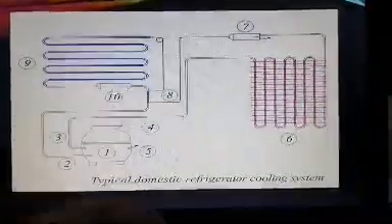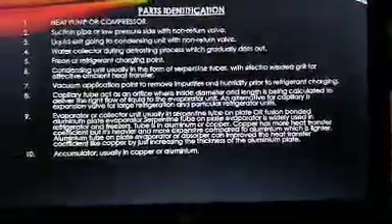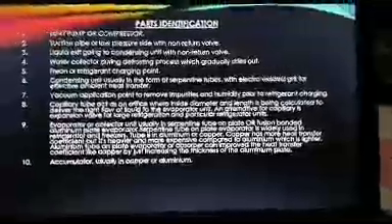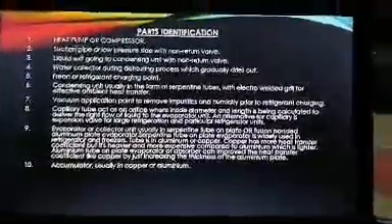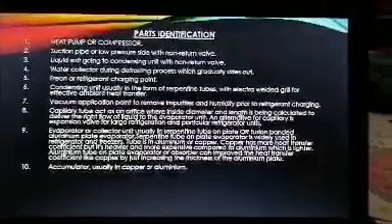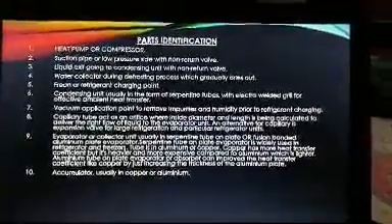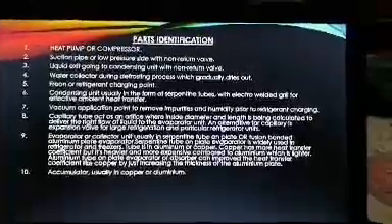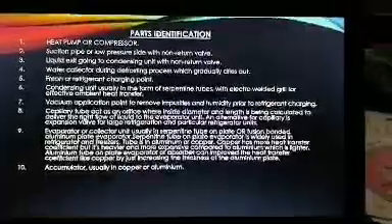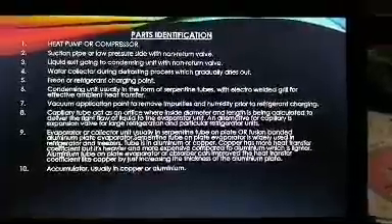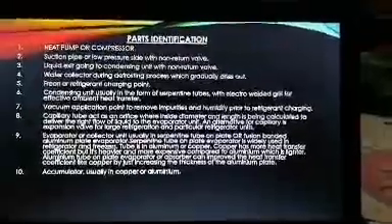Number 9, evaporator or collector unit, usually in serpentine tube or plate or fusion bonded aluminum plate evaporator. Serpentine tube on plate evaporator is widely used in refrigerators and freezers. Tube is in aluminum or copper. Copper has more heat transfer coefficient, but it's heavier and more expensive compared to aluminum, which is lighter.